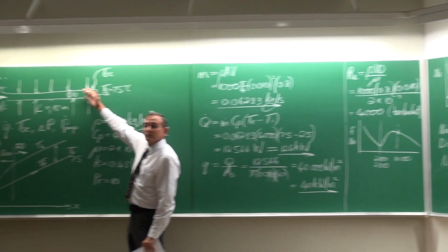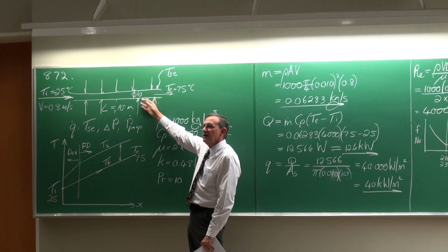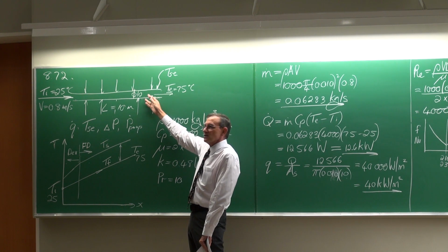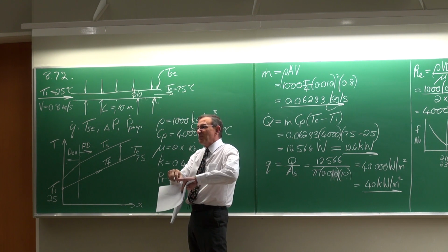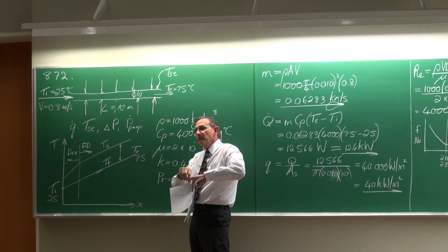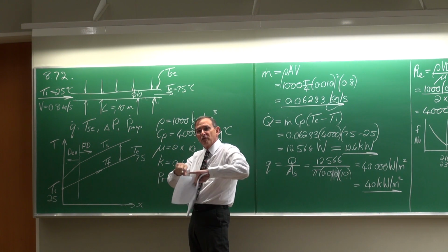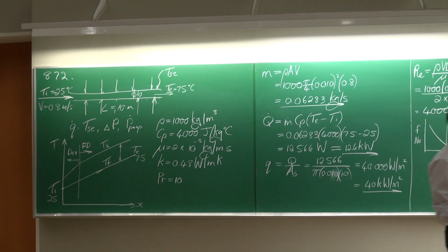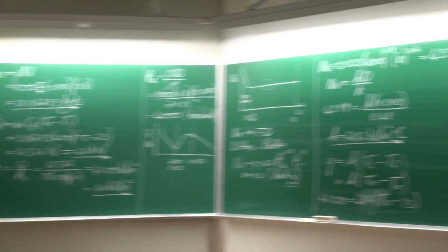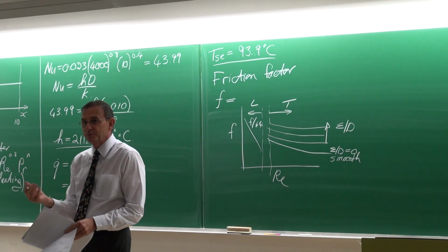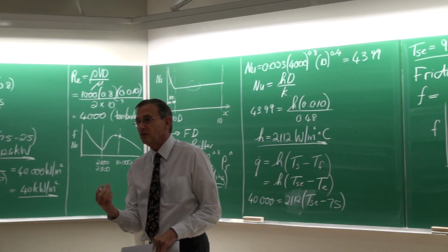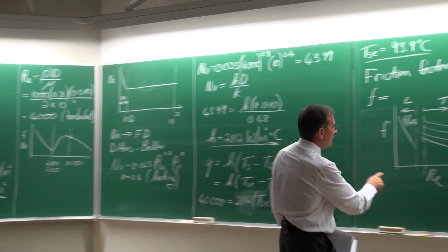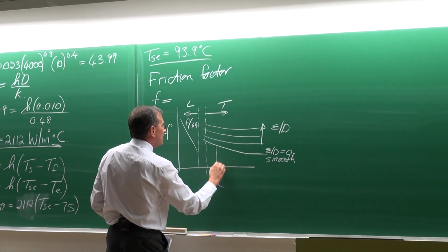Normally, except if it is specified differently, we will assume it's a smooth tube. And your question would be, is that a good assumption? And the answer is yes. Any copper tube or steel tube these days is being made from hard-drawn or soft-drawn tube, and you can go and measure it. They are really, for all practical purposes, smooth. In the old days, when the tubes, which were then called pipes, were cast, they were actually very rough on the inside. But these days, for all practical purposes, you can assume they are smooth. And that's what we're also going to do. So that's now very easy.